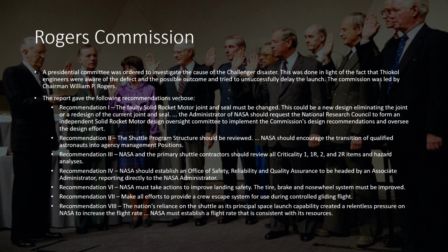The faulty solid rocket motor joint and seal must be changed. This could be a new design eliminating the joint or a redesign of the current joint and seals. The administrator of NASA should request the National Research Council to form an independent solid rocket motor design oversight committee to implement the Commission's design recommendations and oversee the design effort. Thus, the faulty solid rocket motors were replaced with a newer design.